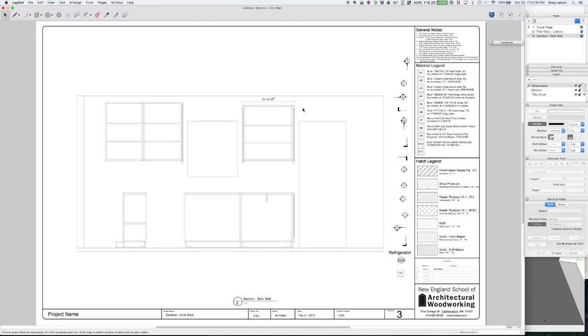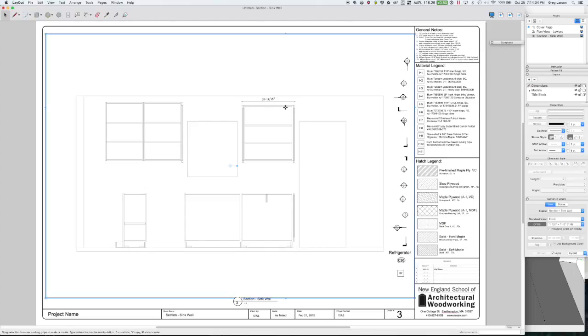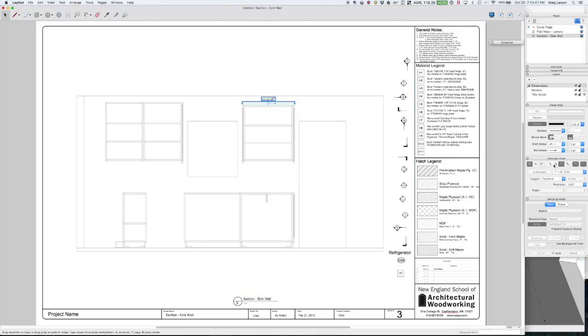Now, there's one subtlety here. I don't know if this dimension is actually correct. My scale for my SketchUp model here is 1.5 inches equals 1 foot. But my dimension, there's a dimension style here. You have a dimension scale. And you can have it auto scale. Notice it just changed to 33.5.